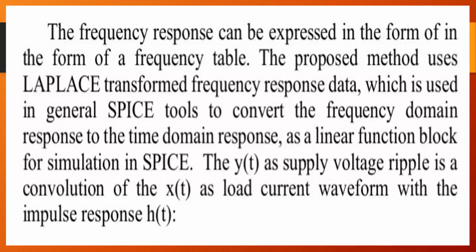The frequency response can be expressed in the form of a frequency table. The proposed method uses Laplace transformed frequency response data, which is used in general SPICE tools to convert the frequency domain response to the time domain response as a linear function block for a SPICE simulation.